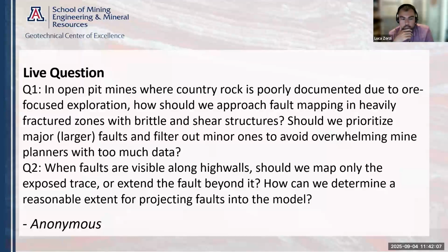Oh, no, it was just two quick comments on what you discussed on question one. Really, the prioritization of larger or smaller scale faults all depends on the scope of your mapping at that point. The small scale structures, as Ian was hinting, could be very important for your bench scale analysis, your stability at the bench scale or a couple of benches, or even an interramp level thing. So it really depends on what you're trying to achieve. But pinning down the major ones first and then working your way down to the smaller ones is also a good approach.